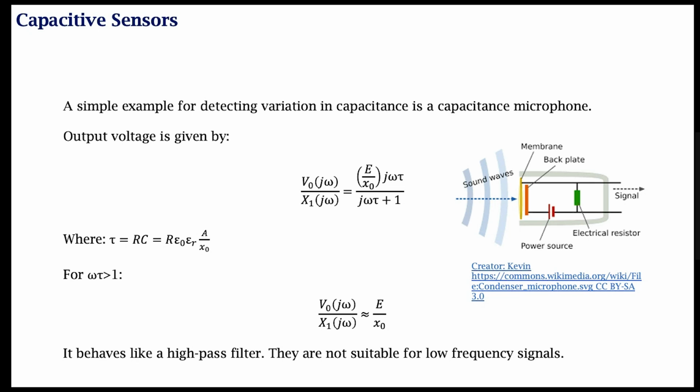Now, that cutoff frequency at which this is going to be highly sensitive is defined by the specific characteristics and applications of interest. But please do find out why this RC circuit is considered a high pass filter, and how I can design an RC circuit as a low pass filter. Another exercise for you from your circuit theory. If you do not know that much circuit theory to understand why this RC circuit is a high pass filter, and what is an RC circuit that acts as a low pass filter, do check standard electric circuit theory textbooks like Nilsson, for example.